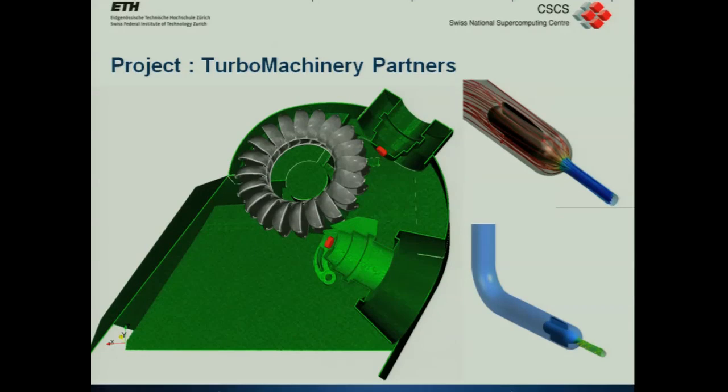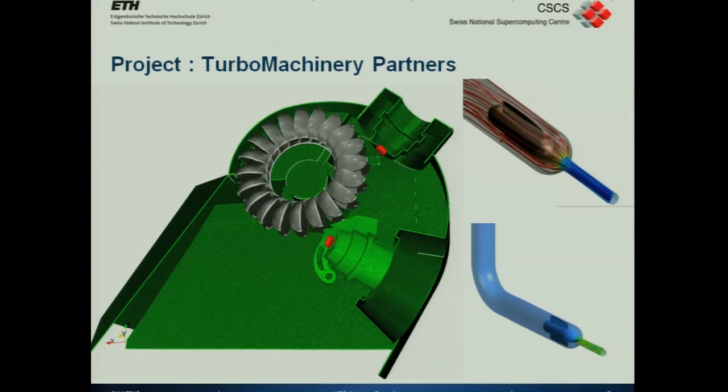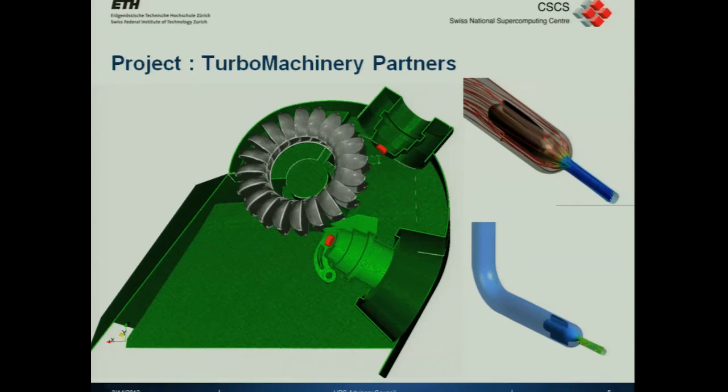Over here you have jets. Water comes down, there's a lake on the top of the mountain, the water comes down a pipe, it comes out of this jet here, hits this bucket, and then it splashes out. Now the buckets all spin round, and the shape of this jet actually plays quite an important part in the momentum transfer, the energy transfer into these buckets. And these wheels are usually mounted in a horizontal frame of reference, so they spin like this rather than like a wheel. And what happens is the water splashes out, and this casing is all basically sealed.